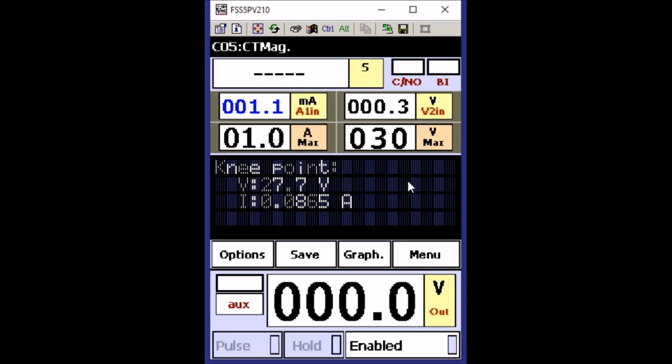If you extend the search range too much, chances are that the function will not be able to distinguish the saturation voltage. So you have to always do your best to start searching as close to the theoretical value as possible. Have you got me?